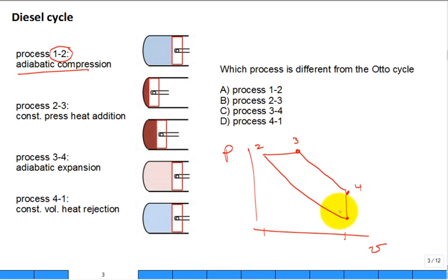And then in the approximation of the diesel cycle, you'll then replace that exhaust and intake with just a constant volume heat transfer. So this is the big change right there, the constant pressure heat addition. What did we have? We had a compression ratio, r as the symbol. Was that V1 divided by V2? Is that our definition of the compression ratio?